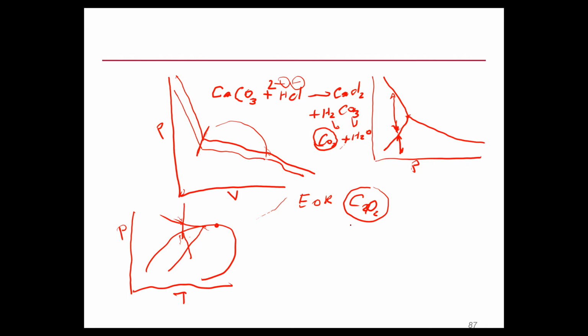The problem I found, in my opinion, I might be wrong, is that a lot of companies use titration as the base test for modeling asphaltene. I don't think that's the right approach. I think you have to simulate the process itself. If it is depletion, we need to simulate depletion. If it is acid, we need to simulate that to get a correct representation of asphaltene.